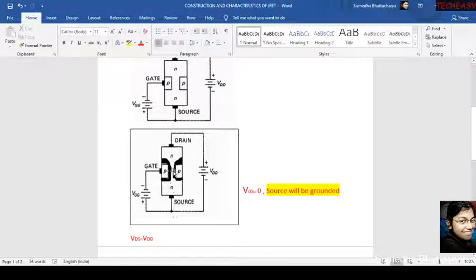These two types will never be attached. The depletion region will be very narrow, and at a certain time, because it is a variable voltage, the current will be saturated. That means after that time you can increase the voltage, but the current will not increase anymore. The current will saturate.